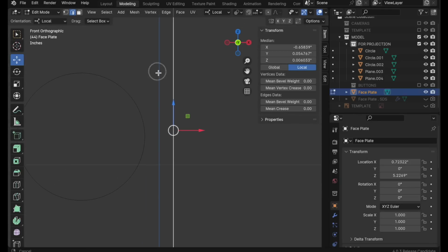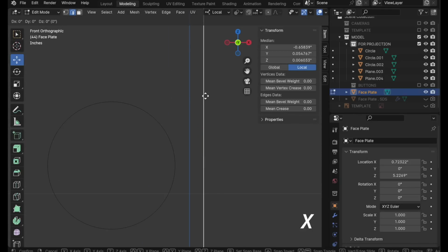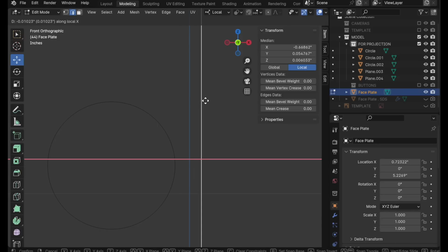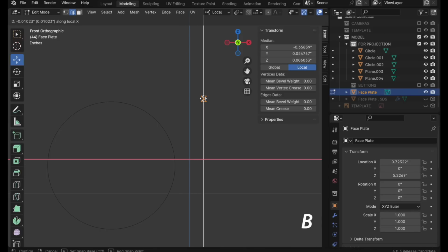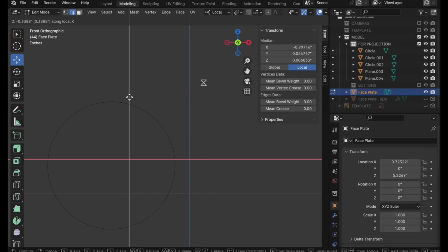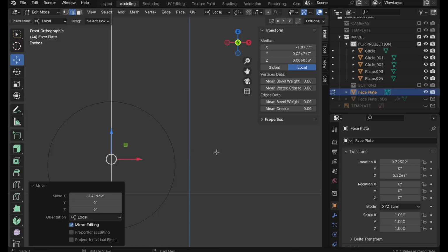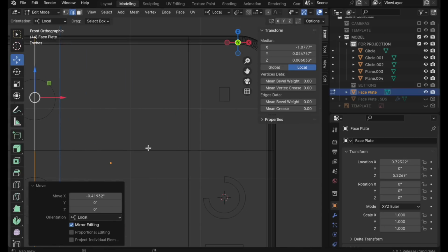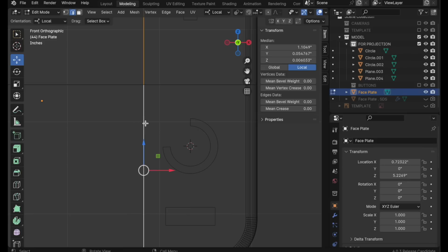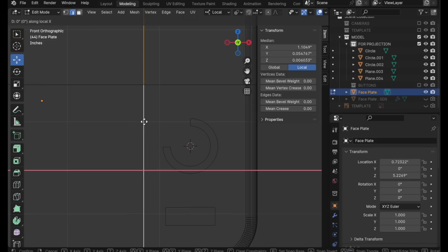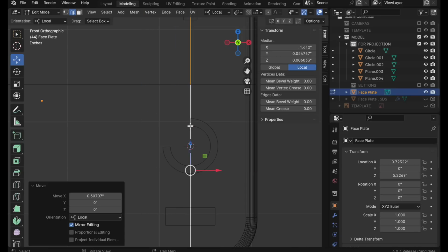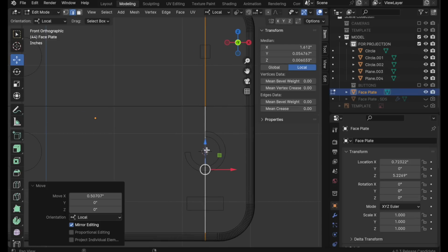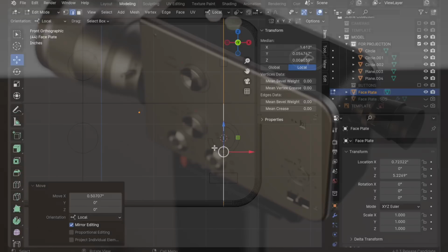Let's zoom in a little bit. Press the G key and then X, but we want to snap it. So we're going to use a new function in 4.0. Press the B key, click the first point, which is the snapping location on the loop, move it over until we get to that top vertex point on the circular area, and release, and it snaps. Super useful. Okay, so let's do the same thing over here. Double click to select that loop, GX, press the B key, click here, and then come over and click the center, and that loop is going to affect all of these 3 cutout objects.